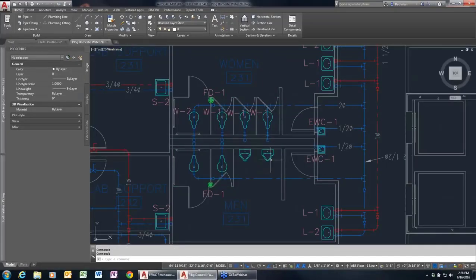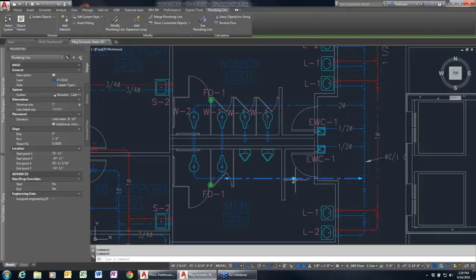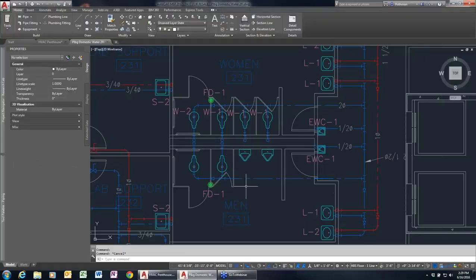What I want to show over here is basically, as I said, in plumbing lines, all we're doing is showing things schematically. So we're not necessarily showing a pipe where it's actually going to be modeled or something. I can show it wherever I want. But there's still intelligence associated with this. Even though this is just a single line 2D object, it knows that it's, in this case, a 1-inch pipe. It's got no slope. It has an elevation associated with it. It knows that it's copper, etc.